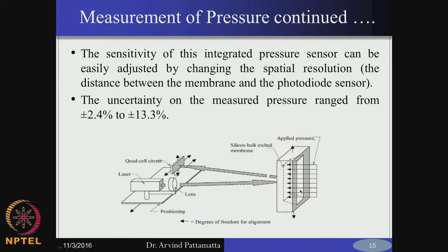So, now we have to have a laser source, and a sensor which can detect the intensity of the laser light that is reflected or deflected from the silicon membrane. Okay. So, a laser source will be illuminating laser light onto the membrane. Now, depending on the deflection, the angle of the deflected light coming from the membrane will be different. If there was no deflection, it will reflect at a particular angle. Now, due to deflection, this angle will change either in this way or this way.